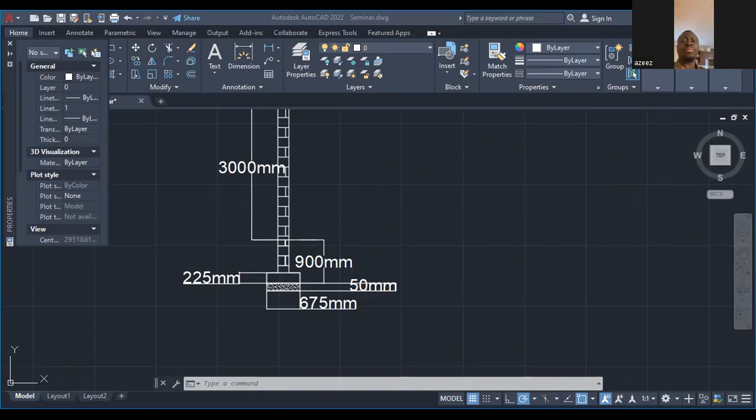when you want to build up quantity for your concrete, you are dealing with volume. So each of the materials will come in volume, though you can also convert it to square meter, by the way. If you build up your rate in cubic meter, it's just a matter of multiplying it by your thickness. Do you get? So it's just the format they want.